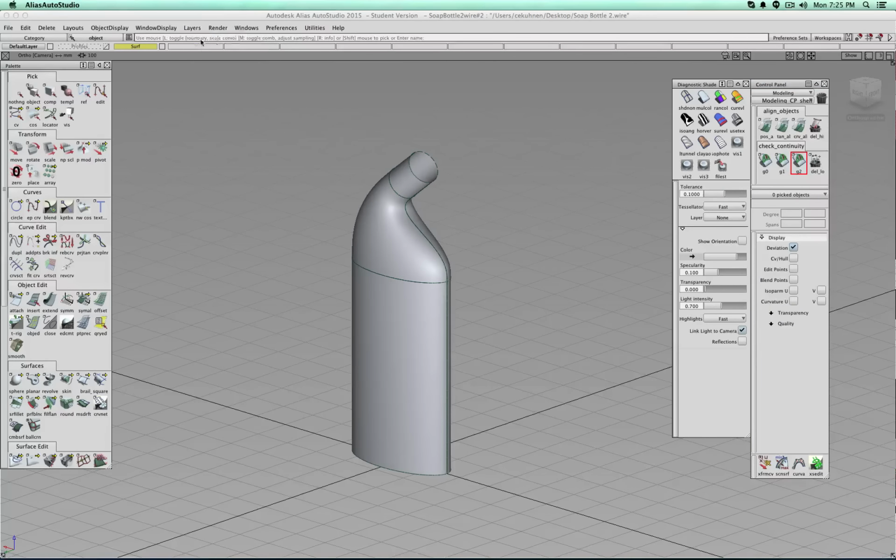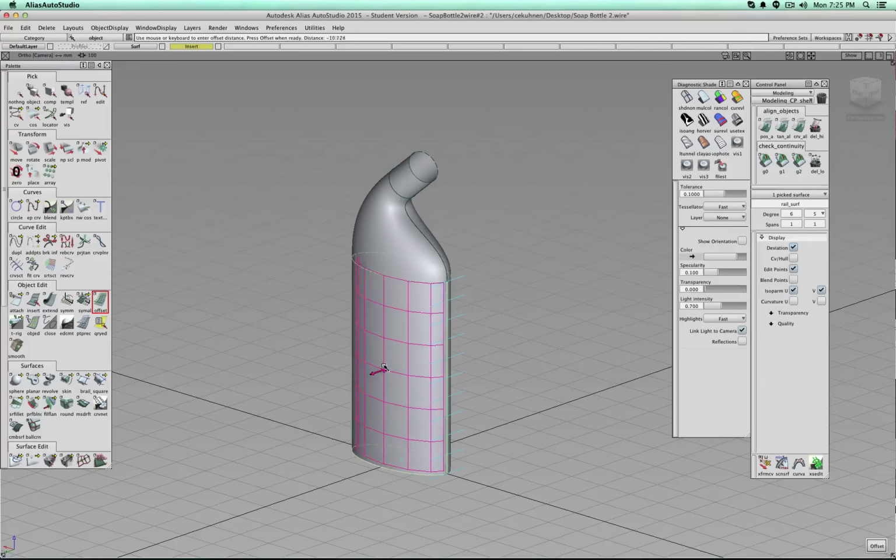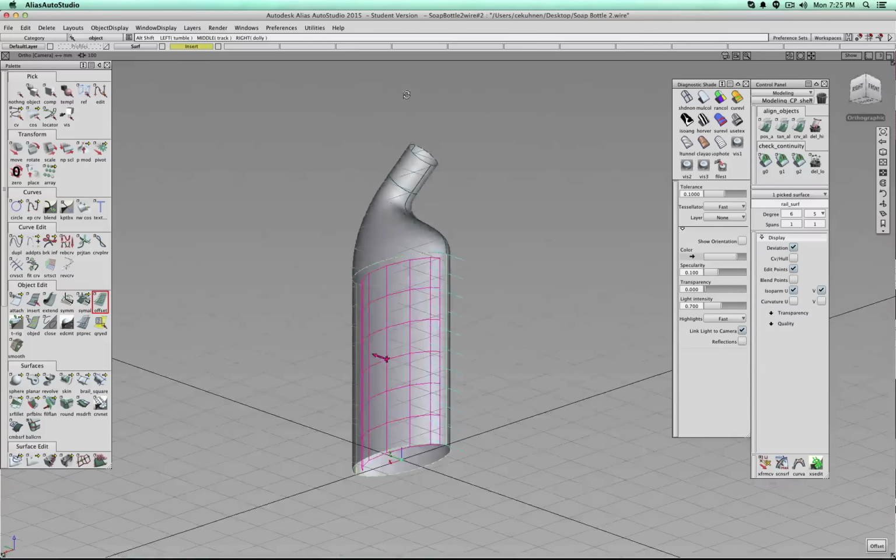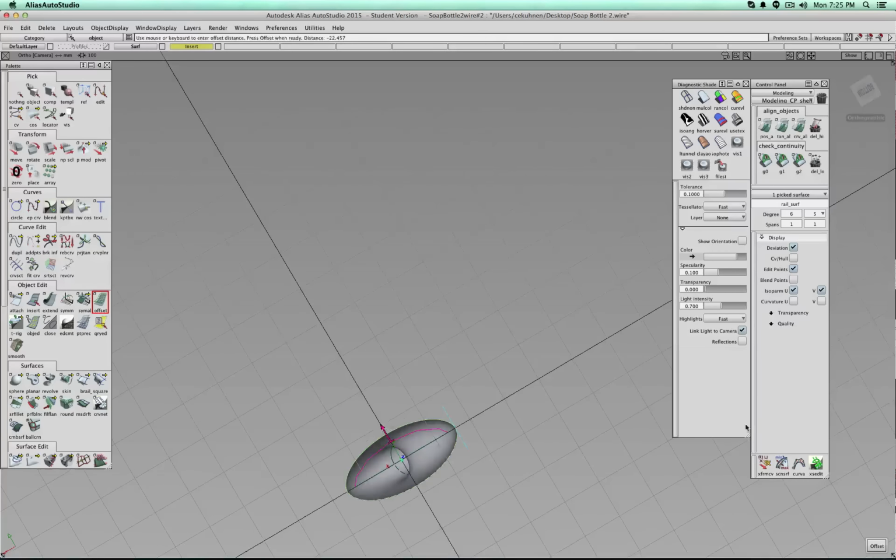And I'm creating a new surface, for example, insert. And I would like to create an offset from this surface. So I'm eyeballing roughly how much I would like to go in. Click offset, OK, and then this surface, I am moving on to that layer.